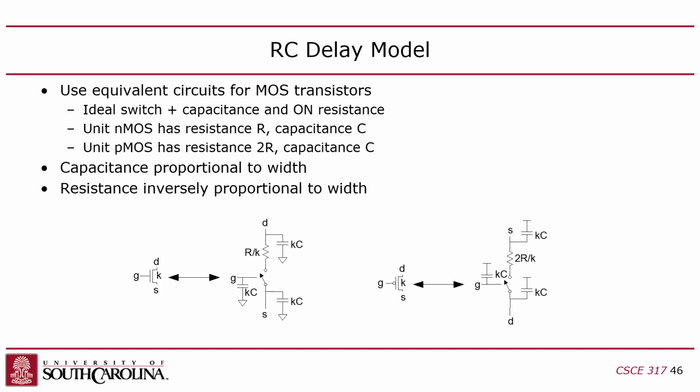So it's kind of complicated because you can increase the strength of a gate, and you have to calculate basically the delay. One way to do it is just run through SPICE. In SPICE, you can have a transistor model, and then you can set up these transistor level circuits in SPICE and run it.